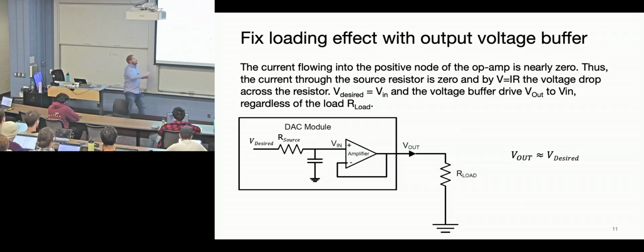The input to an op amp is high resistance, high impedance. It's supposed to be megaohms. So now my I is 0, or effectively 0, right? Therefore, my voltage drop across the resistor is 0. Going through the capacitor, no, so I will erase that capacitor. Let's just say in the steady state, we're at low frequencies.